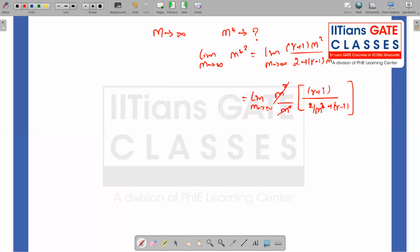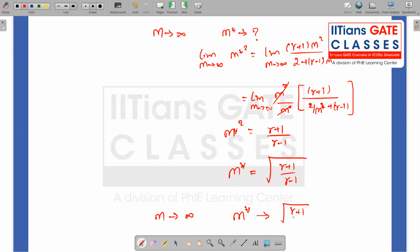Now if I apply the limit M tending to infinity, this 2 by M square becomes 0, 2 by infinity. So this becomes gamma plus 1 divided by gamma minus 1. This is interesting. As M tends to infinity, M star square tends to gamma plus 1 by gamma minus 1, or M star is equal to the square root of gamma plus 1 by gamma minus 1. So it reaches a finite value. It doesn't shoot up and go to infinity. M star is going to be a finite value, right?